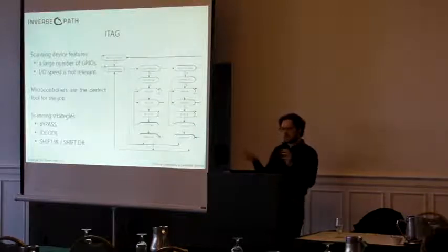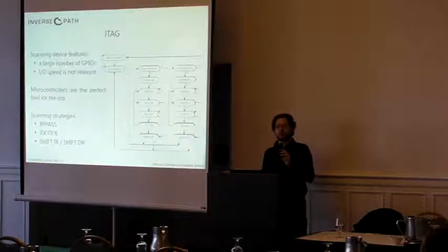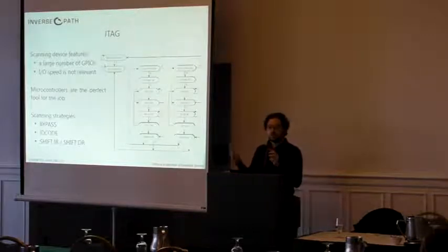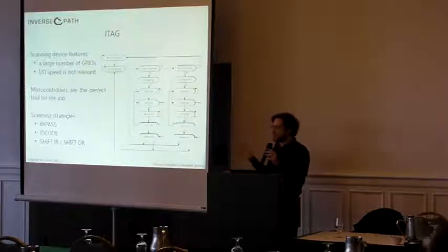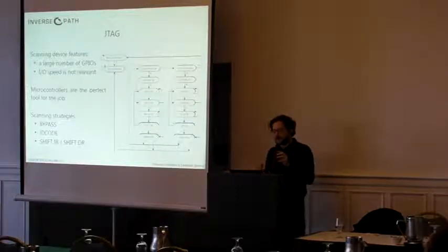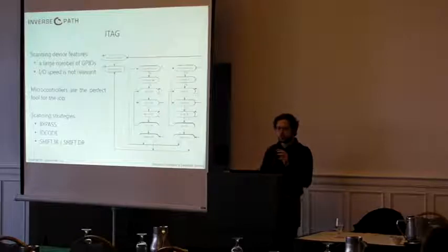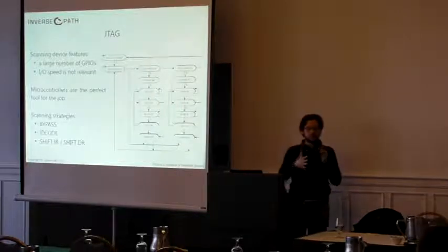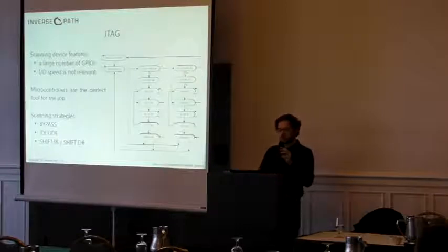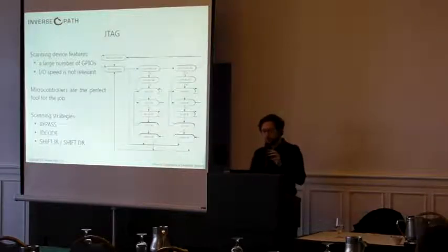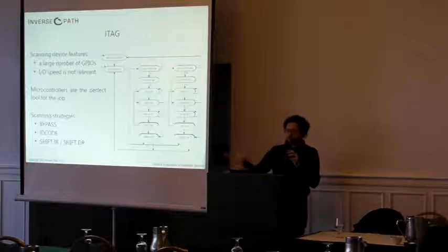But the problem is that, at least in our experience, we have encountered many devices where the standard was not being honored because there was a custom initialization sequence that you really have to know in order to put the system in a state that allows you to work on it. And sometimes it's extremely difficult to probe for this initialization sequence without damaging your equipment, or if you don't have a reference, like a custom debugger hardware which is given to you by the manufacturer and that you can piggyback on to see what's going on, it becomes really, really difficult.